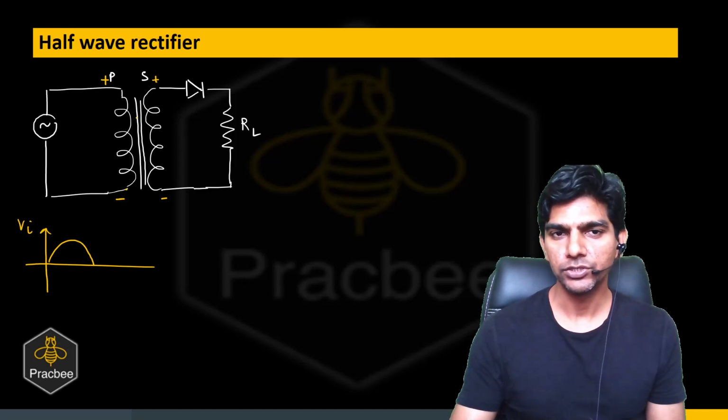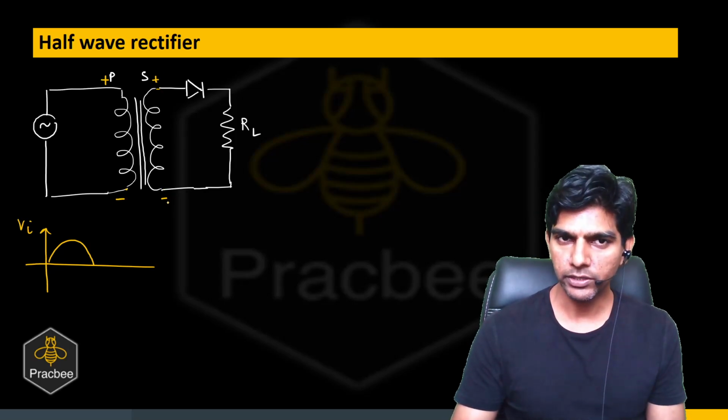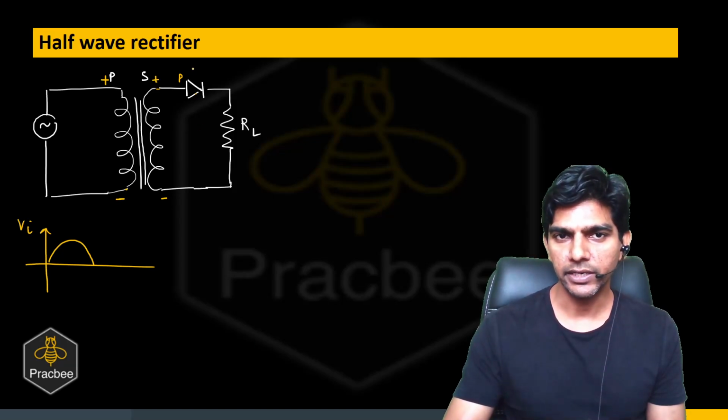Similarly, by mutual induction, the top side of the secondary will be at high potential and bottom will be at low potential. Then the P side of the diode is connected with the high potential, so this diode is forward biased, right?